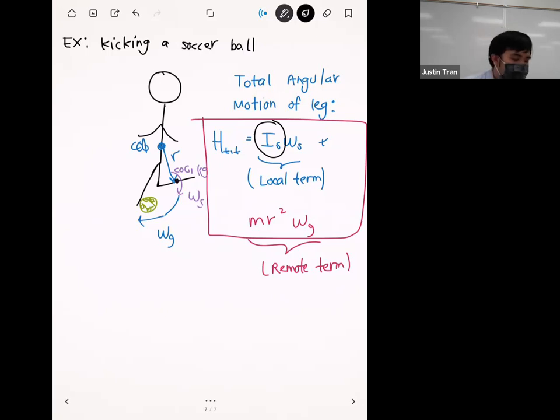Technically, it's not uniform, because the calf could be bigger at the top and smaller at the bottom. Exactly. If you assume it to be a uniform rod, then you have 1/12 m l squared. Because the leg itself is not a uniform rod, you'd have to adjust for that in some way, but I think a uniform rod is a pretty decent approximation.